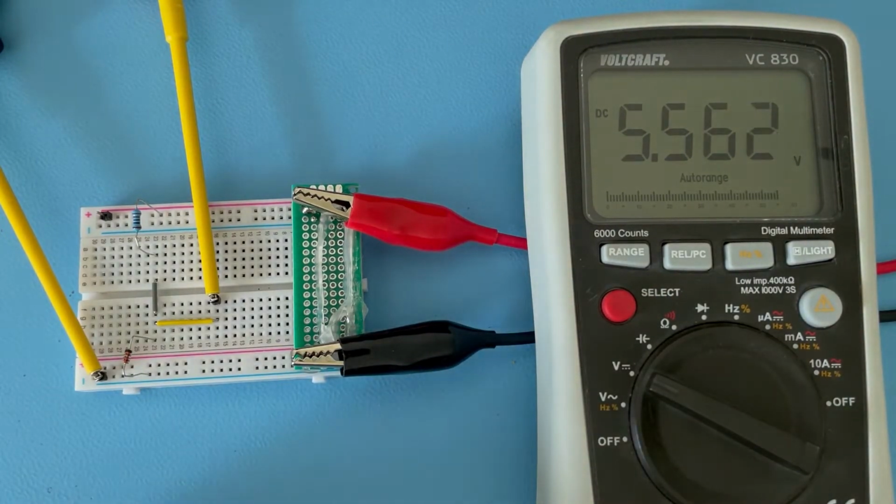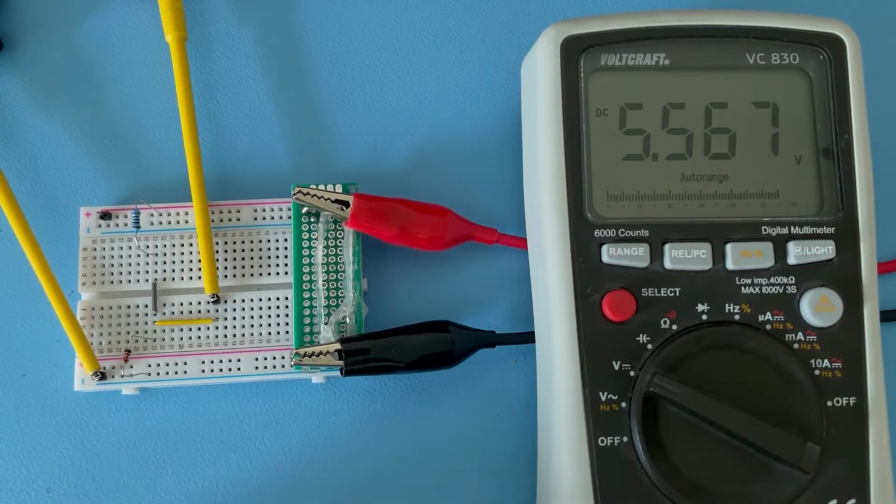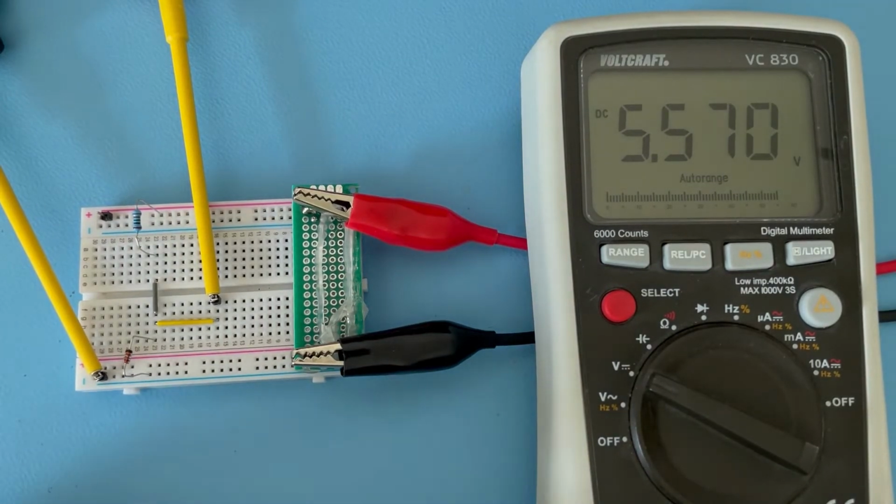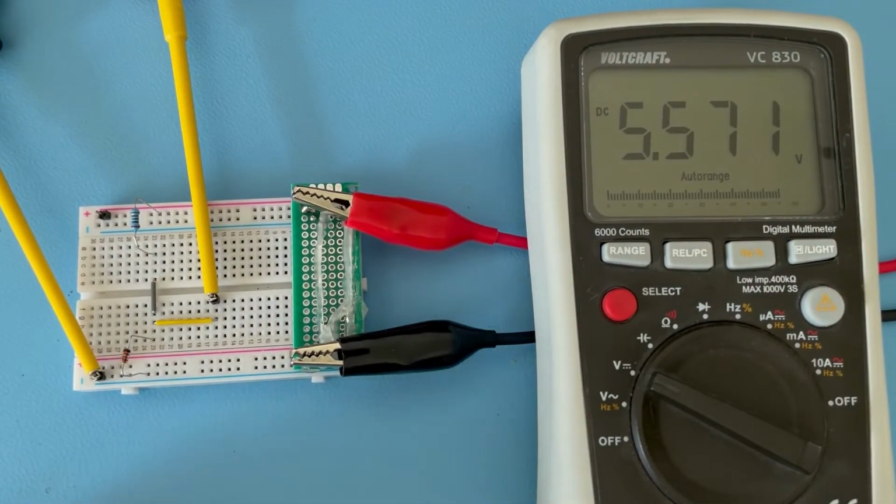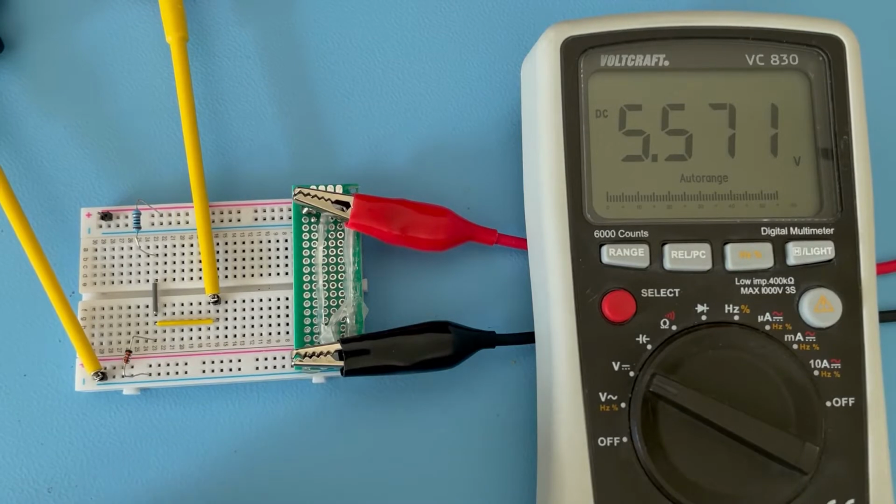And we're measuring a good 5.56. So 5.5. The nominal Zener value is 5.6, and that's good. That's okay for a Zener. I bought a bunch of Zeners just with no quality assurance checked from my side, just a random maybe Chinese package of a collection of multi-value Zener diodes. Okay.